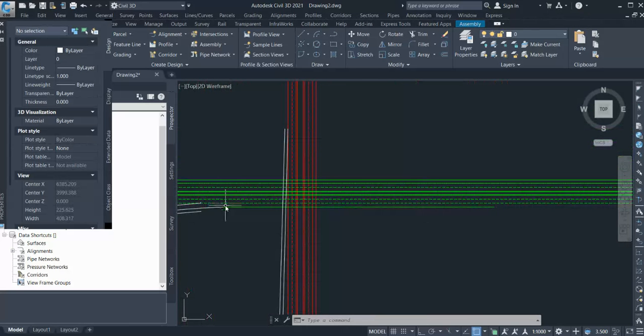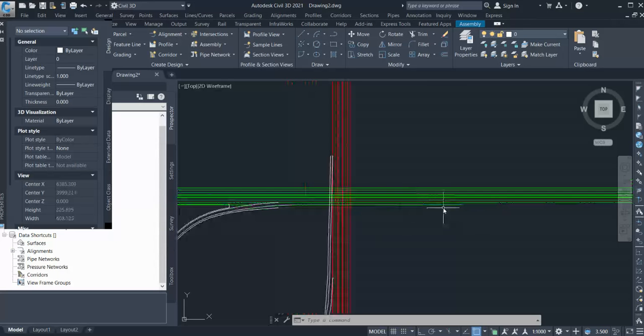Now this section also depends on the traffic and your weaving lane, your diverging merging taper. You should at least provide 170 meter or 180 meter, whatever your merging and diverging standard. So you should provide at least that lane between these 2 points. So this is also another option.